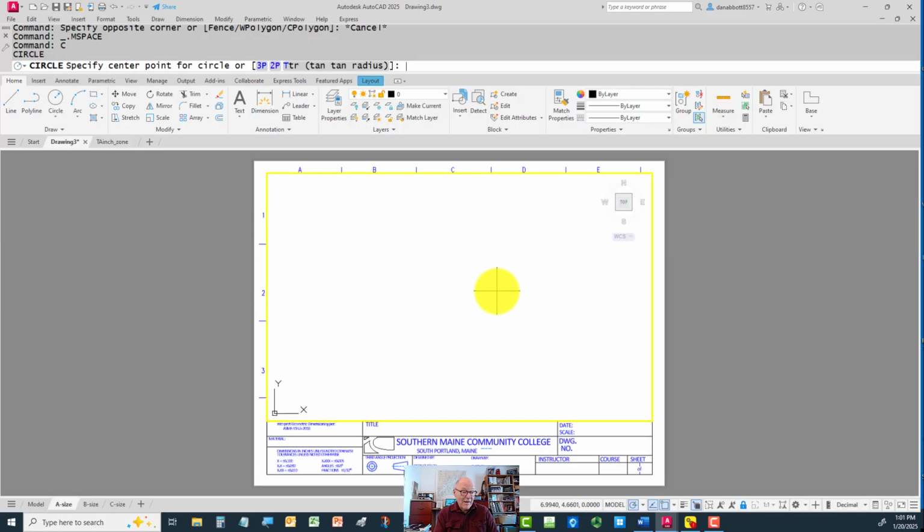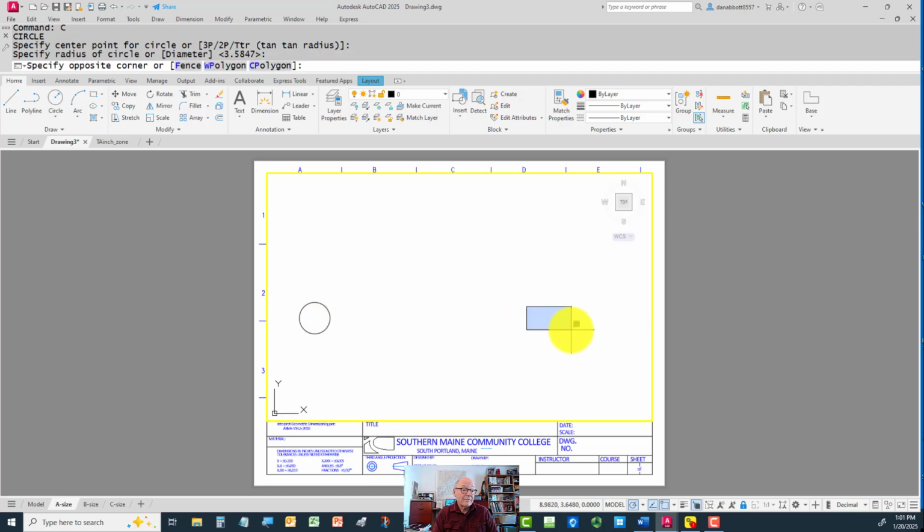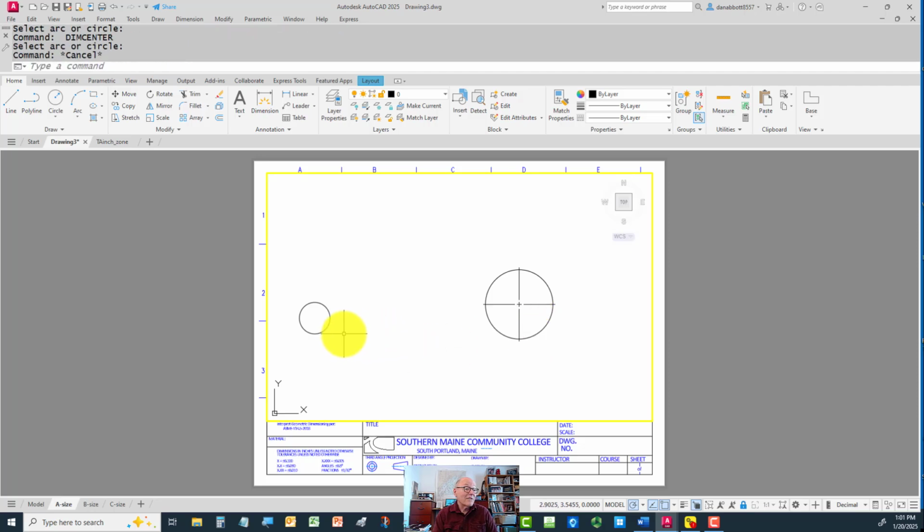And because I've got my dimension style set up, if I start putting in my center marks, center mark looks good here, and I put that on the dimension layer, of course. They're nice and consistent. Again, don't do this. Don't go to the ends of these. This is what a lot of people do because there's not supposed to be a gap in that line. In fact, it's specifically prohibited from having breaks in lines unless they cross an arrowhead. So I would just go to the end of the crosshair when dimensioning in AutoCAD. Now that gives me the actual dimension, and it still looks the way it's supposed to look. Don't forget, of course, that should be on a layer that has thick lines.